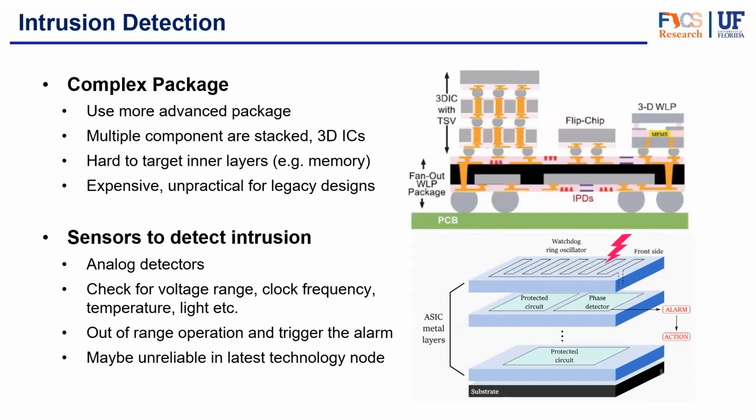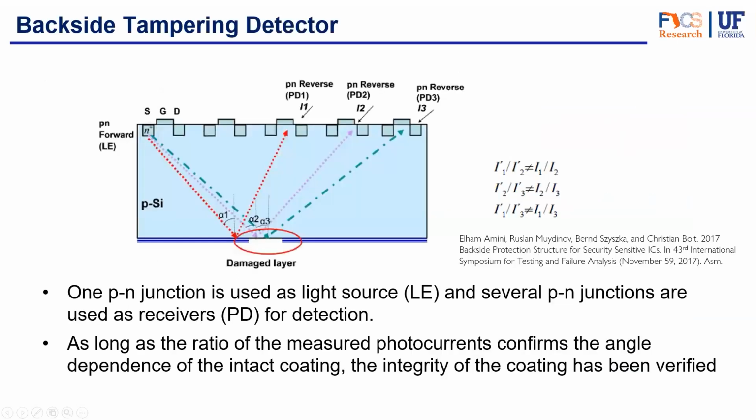At the same time, we have sensors that are sensitive to changes of clock frequency, temperature, and voltage, and any out of range physical characteristic will trigger the alarm, so they detect such attacks and prevent them.